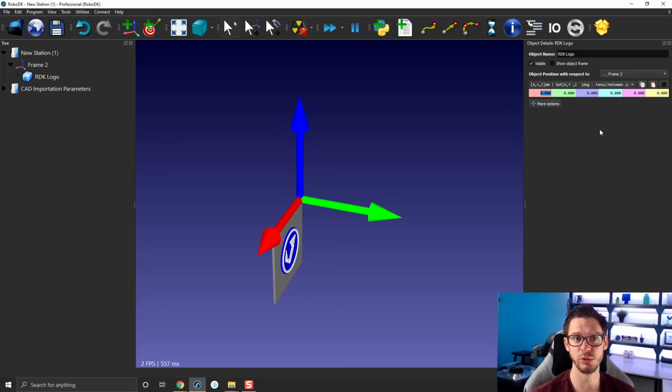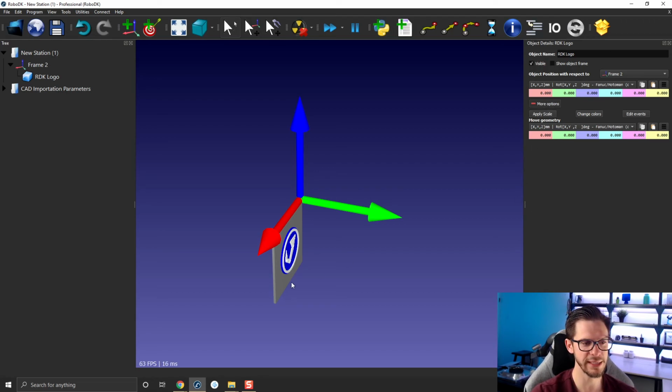But when it comes to realigning the object with respect to its reference frame, as I already showed you before, with the tool, I'm going to press plus here. And starting from here, I'm going to use my scroll wheel and find the right rotation for this one. So something like that would make sense.